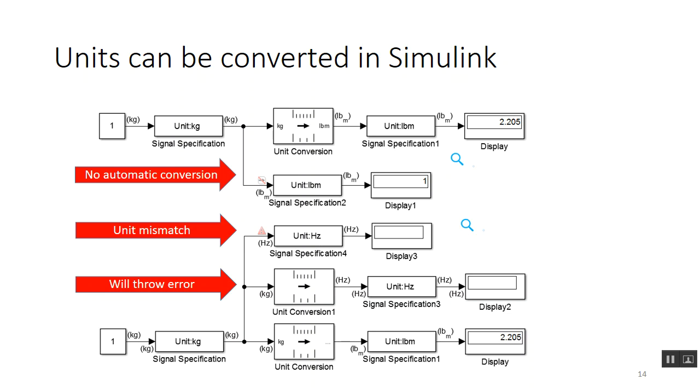Well, part of the problem there is that it has that back propagation and forward propagation, and these share the same node. So it doesn't really know what to do with that. But it's displaying 1. It failed to do any conversions, so 1 kilogram came in, and if it was correct, it should say 2.205, but it says 1 pound mass out. Do you follow what I'm saying?